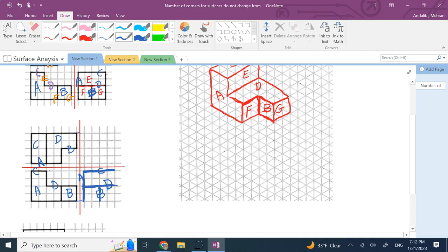So now I got D, and the question is, what about the rest of the right view? Well, as you can clearly see here, there are two edges missing in the right view. One is the bottom edge, and I can see the entire bottom of the object. And one is the right edge, and I can see the entire right edge of the object. So I can draw the entire right edge, and I can draw the entire bottom edge. So this is already my right view, which you can see on the top. And that's it, I'm done.